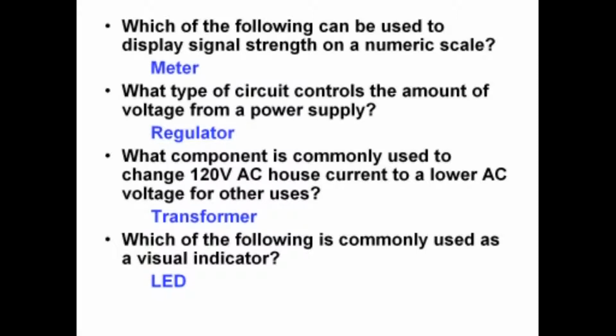So if I have my radio transceiver hooked up to a power supply, it uses very little current when it is receiving. It uses much more current when it's transmitting. The regulator helps keep the voltage from changing when I change from the high current to the low current. So I like to have a regulated power supply to keep that voltage constant, or as constant as possible.